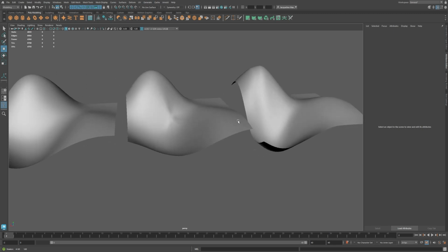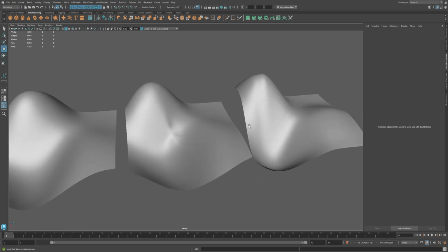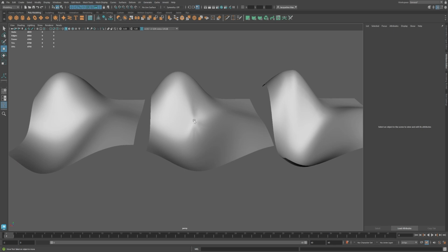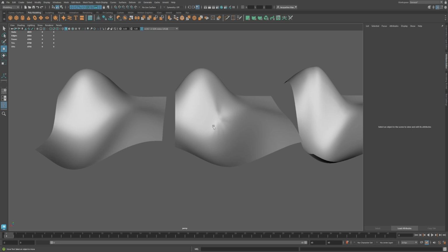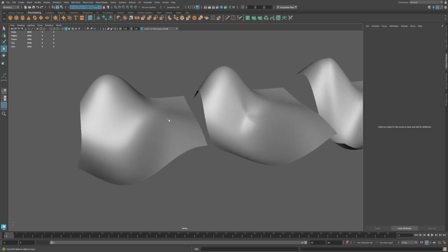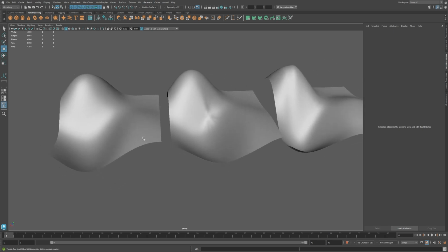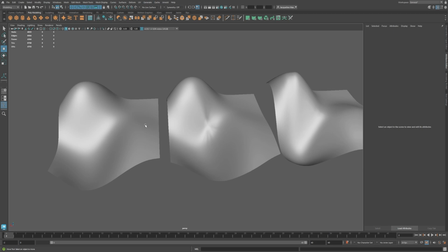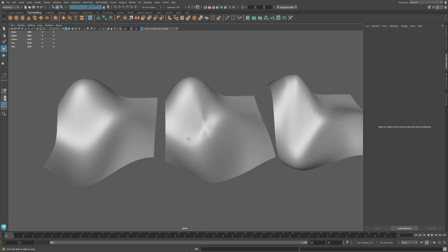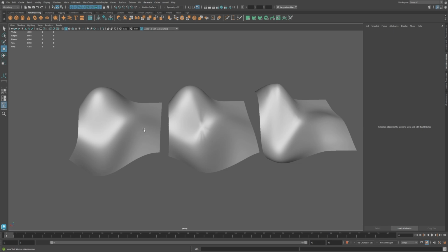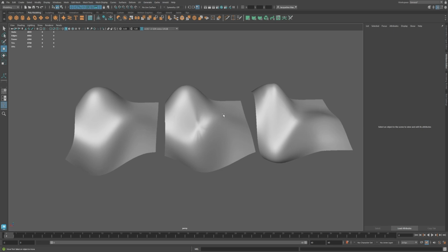A lot of these ripples, just a lack of control. Here was where all the points were converging, and we can see that starburst effect and a bunch of pull on it. And then here was the original clean mesh, and you can see that it handles that deformation much better. So this would be the ideal situation to avoid triangles on any mesh that's going to be organic, or if you're going to do it, to make sure it at least is working with the shape or is in an area that isn't going to deform.